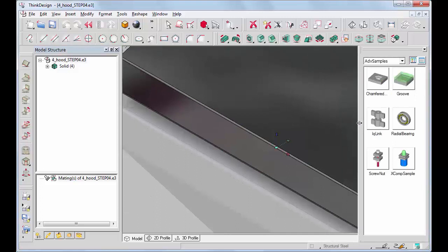After narrowing the smart object library panel, which showed up on the right, so as to make the graphics area larger and better appreciate the model, in the drop-down list on the panel, let us select the library of the sheet metal objects, named SheetMet. And in such library,